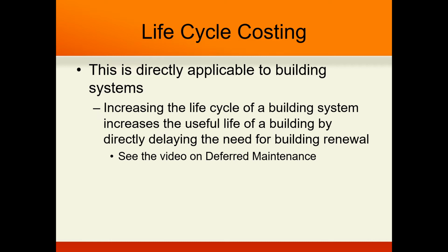For instance, if the building has a life expectancy of 50 years, and you put a 40-year roof on it, you literally only have to replace it basically about 10 years before the building's useful life goes out. If you put a 20-year system on it, now you're going to put on the roof you begin with plus 2 other roofs before you hit that 50-year mark.